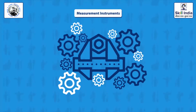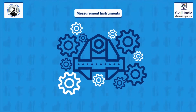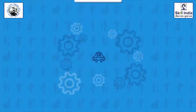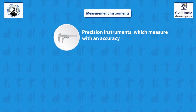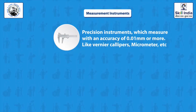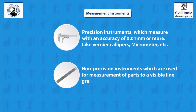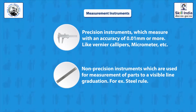Now we will learn about measuring instruments. A measuring instrument is any gadget which you can use for measuring a physical amount. They are classified into 2 types: precision instruments, which measure with an accuracy of 0.01 mm or more, like Vernier calipers, micrometer, etc. And non-precision instruments, which are used for measurement of parts to a visible line graduation, for example, steel rule.